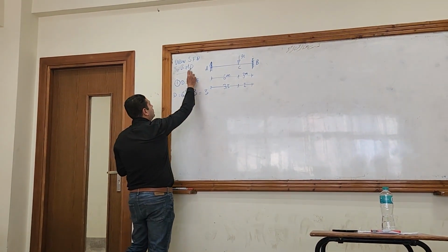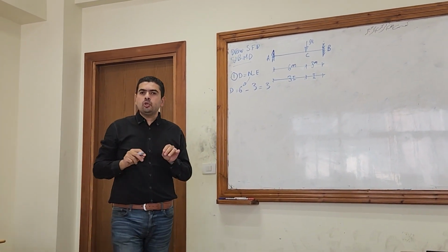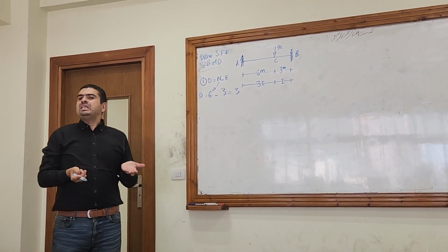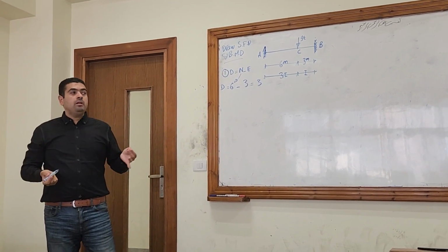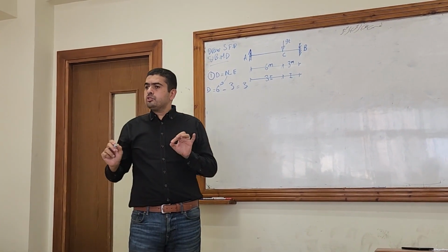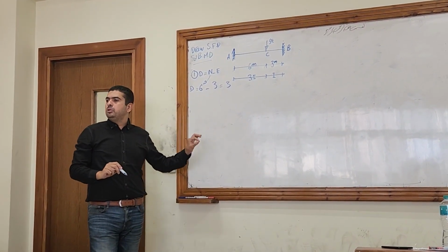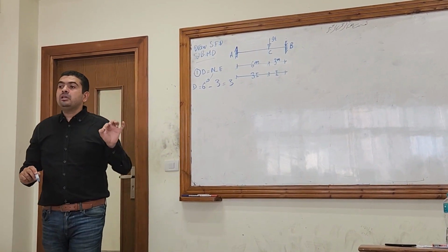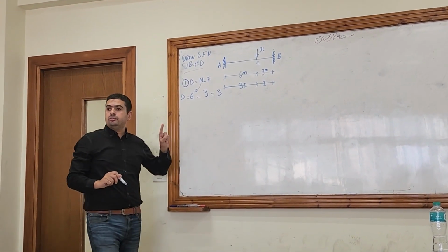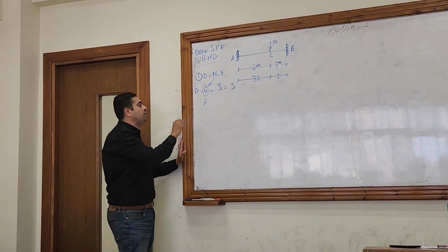Let's see the requirements. As I told you from the last example, you will not be required to draw the normal force diagram, right? So you will not need the horizontal reactions. The horizontal reactions, you need them only when you are drawing the normal force diagram. Here, you only need the shear force diagram and the bending moment diagram, so you don't need the horizontal reaction, right? So when you find more than one horizontal reaction, just remove them from the reactions. So the 6 will be 4.